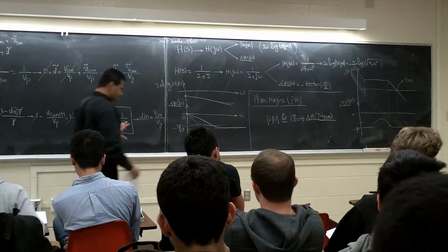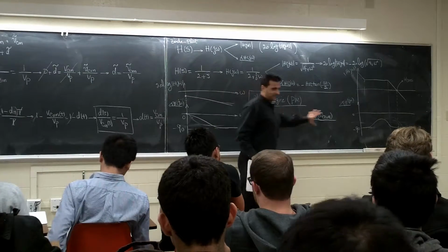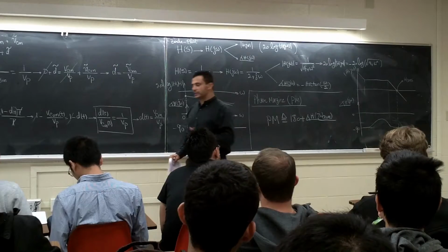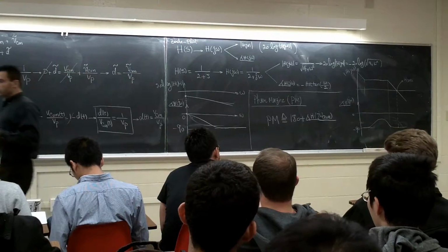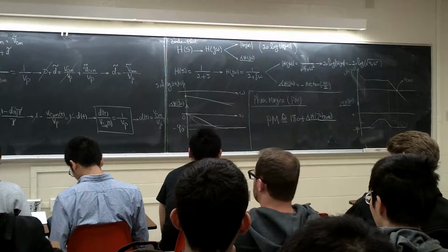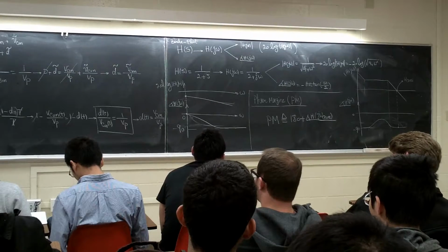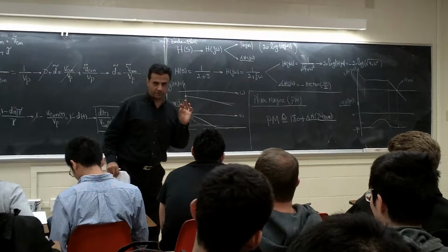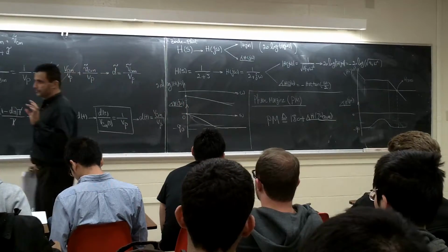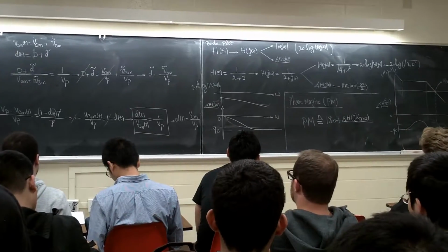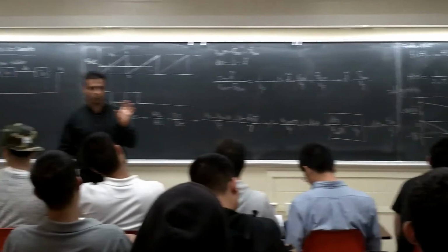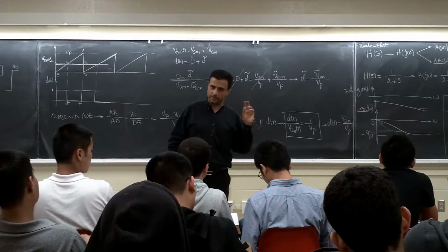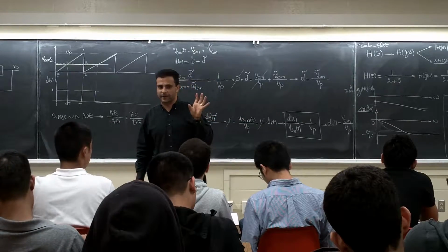Now, for a system, so what's the definition, why are we using this one? I'm not going to get into the detailed control theory, but for a closed loop system, if the open loop system transfer function has a phase margin of 45 to 60 degrees, this is a very good number, 45 to 60 degrees. This is the goal for us. That system is pretty stable. We're going to use this one later.